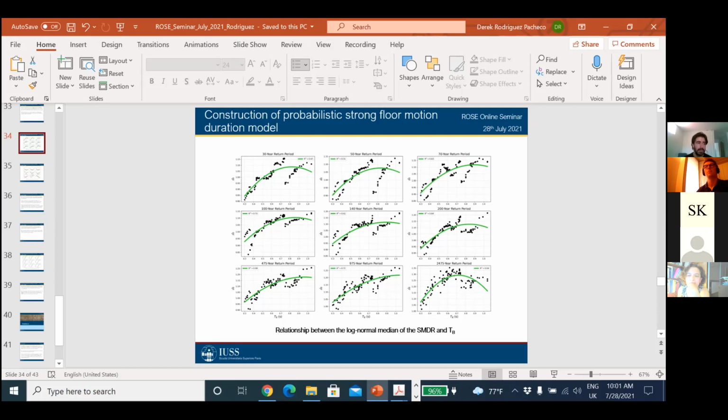In the case of non-structural elements, this is not the case. I know for a fact that very few seismic performance factors for non-structural elements have a rock solid basis. The only one I remember right now that is very well documented is for light partitions, because a study was done at the University at Buffalo by Professor Filiatrault. But besides this, I'm not aware of any other seismic performance factor for any non-structural system that was developed with a strong experimental campaign.